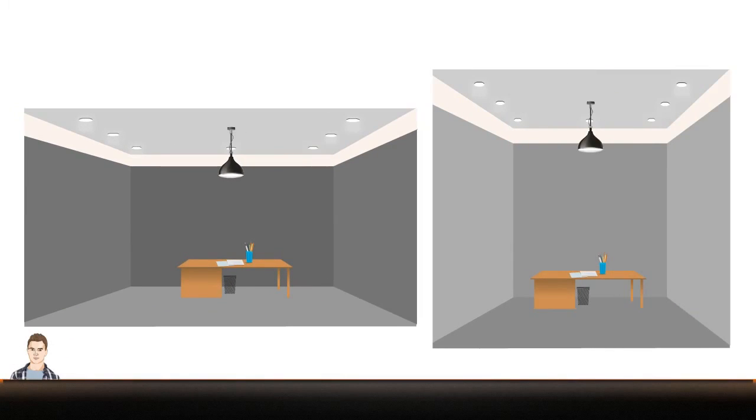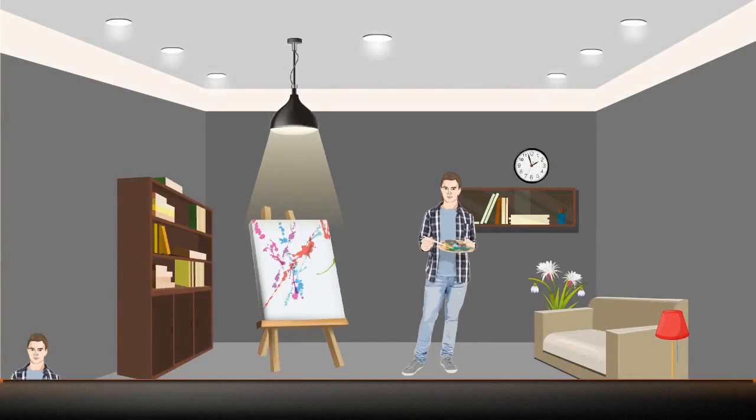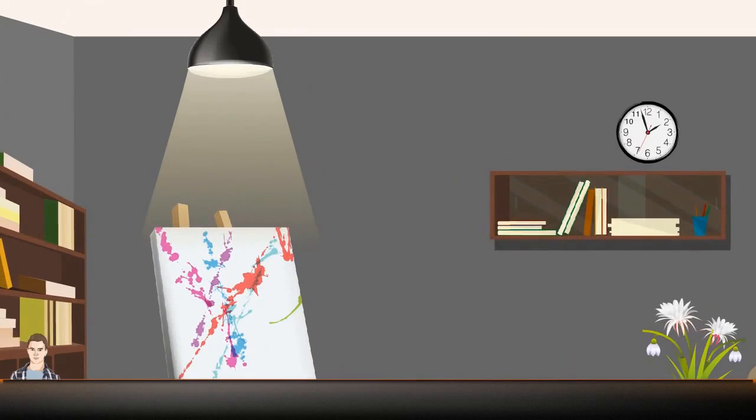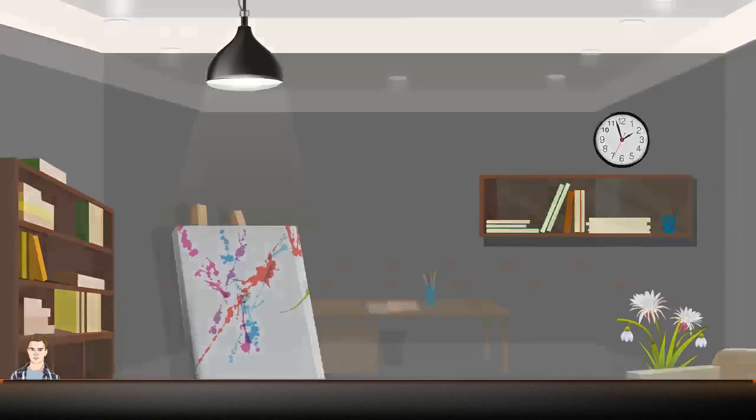Another factor that impacts the calculations for the lighting design is the room geometry. Two rooms with the same reflectance levels, but with different shapes, can produce different calculated results. Next, we will learn about the maintenance factor, which makes a significant difference to the calculated results. This factor is used to determine the depreciation of a lamp or a reflective surface over a period of time.